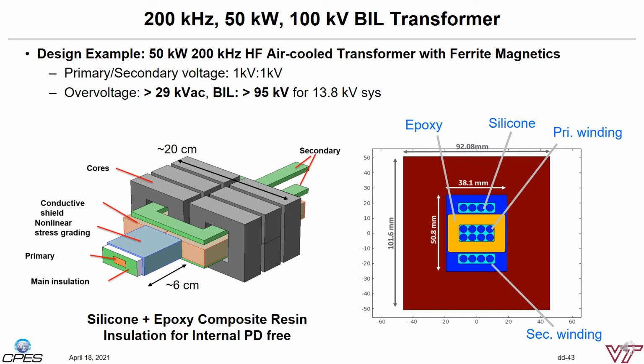The low viscosity silicone is used to pot the lead wire first in order to push out air voids in the lead wire. Epoxy mixed with inorganic fillers is then applied to create the main insulation barrier. A long bar-shaped terminal is built on the high voltage winding exit to meet the creepage distance requirement. The entire insulation surface is applied with a conductive coating layer to control the E-field.